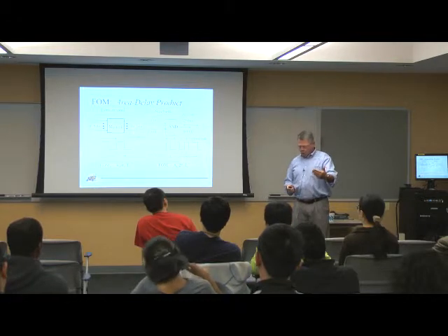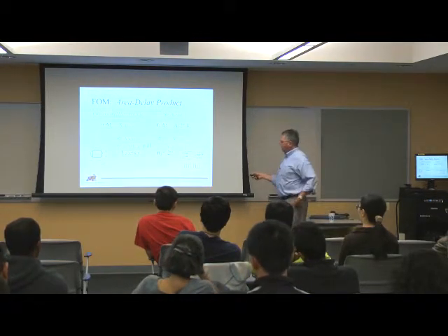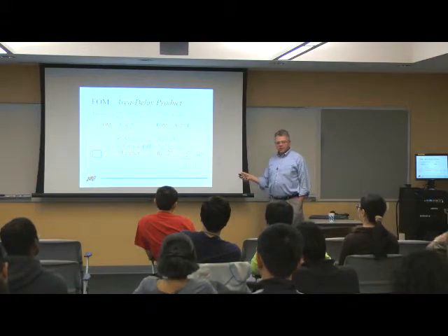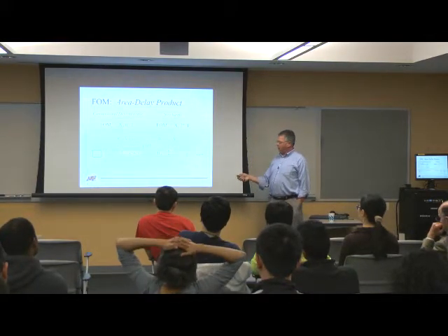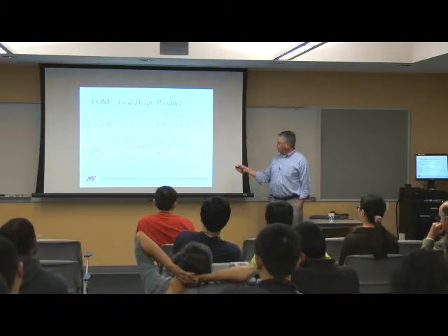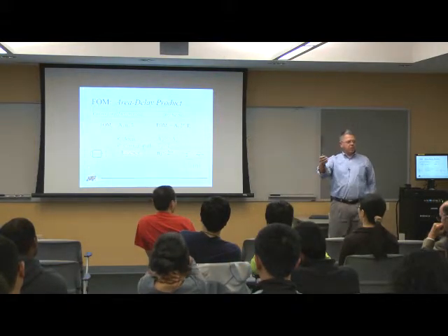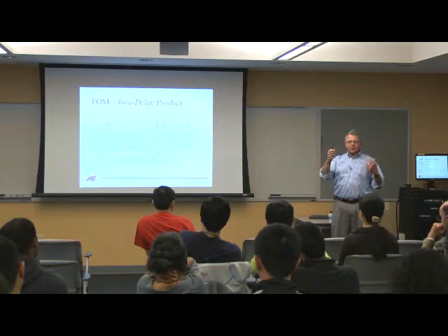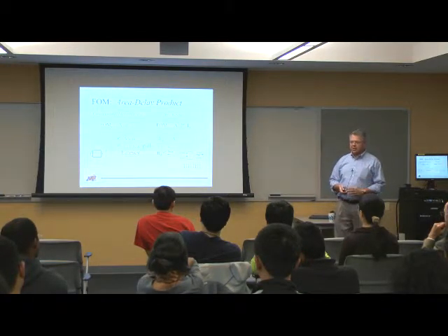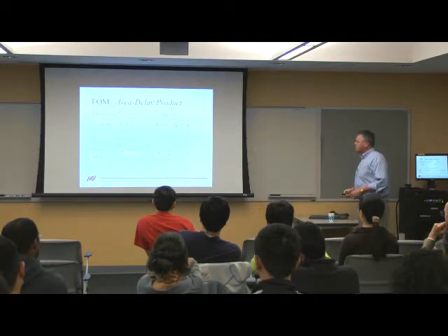So it's going to take a lot longer, but my hope is that the area of the stochastic implementation is going to be so much less than the area of the deterministic implementation that this product here is going to be smaller than the product there. So I'll have a win on this overall area delay product. It may take a little bit longer in latency, but it's so cheap to do that maybe I can tolerate that latency, especially given the fault-tolerant aspects of this.